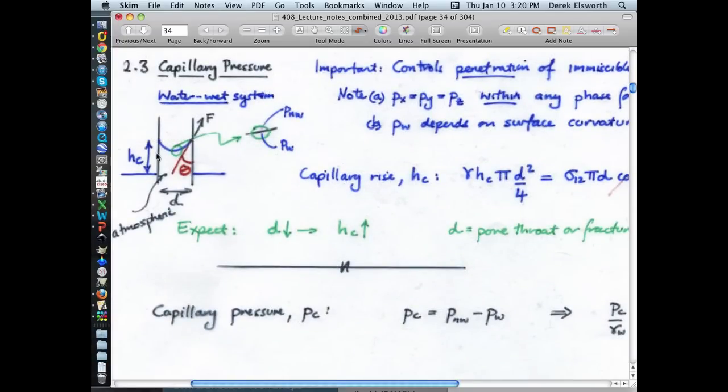And so here's the idea. This is a capillary tube. You put it into water. It rises up to some height. You can do a couple of things, right? You know for sure, since the pressure on this surface here is atmospheric, as it is on this surface here, if you go across a fluid and you're on the same elevation as you go across that fluid, then you know that this point here also has to be atmospheric pressure as well.